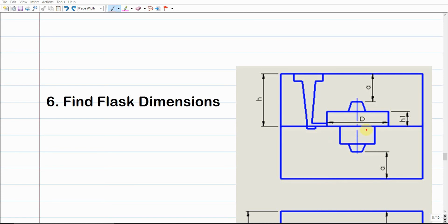But in addition to this, we're gonna add some openings for the riser, and there are some other openings for the gating system, like the pouring cup, the down sprue, the sprue well, the runners, and so on. So when we fill these cavities with molten metal, and then leave it for a while till solidification, as we mentioned before in the procedure of the sand casting process, all of this region will be filled with molten metal, right?